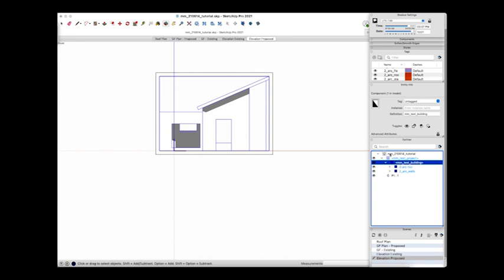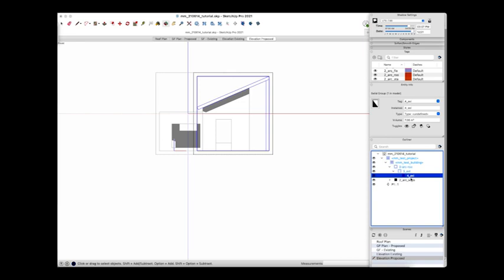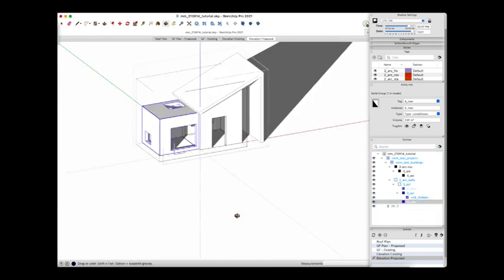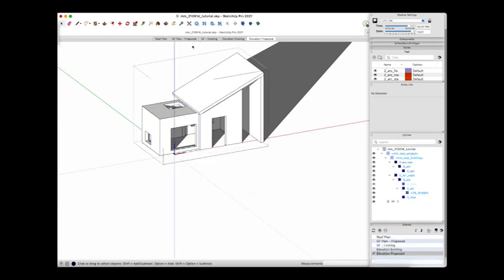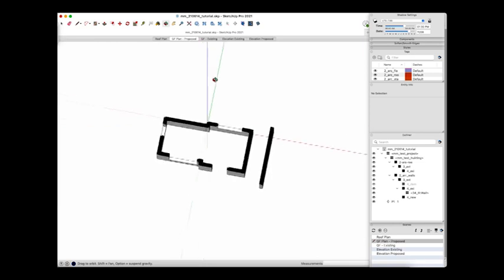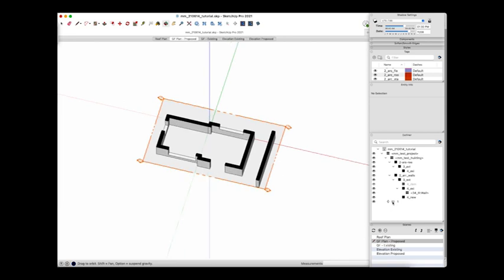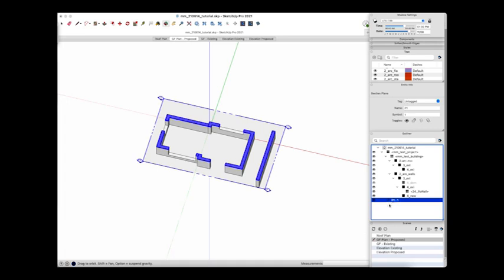SketchUp won't by itself fill in all the information in the outliner. Our suggestion is you do, so that even if you don't know exactly where you are with your tags, it's always easier to go to your outliner and jump straight onto the part of modeling which refers to the existing part of the roof, for instance, or you can jump straight onto the new part of the walls. So that's the basic, and obviously as you start slicing your model with cutting planes, you can also quickly switch from one cutting plane to the next by having all of them correctly labeled here in your outliner.